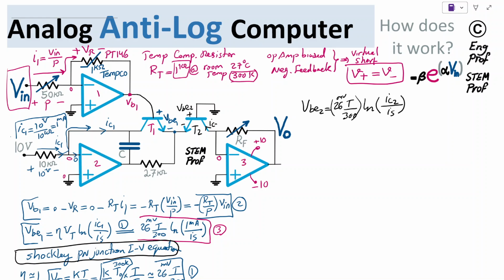That is effectively IE2. This IC2 again cannot come from the negative terminal because the input impedance of the op-amp is infinite. So this IC2 can only flow through the RF resistor and continue through the transistor. On one side we have 0, on the other side we have Vout. So the voltage drop across RF is plus minus Vout.